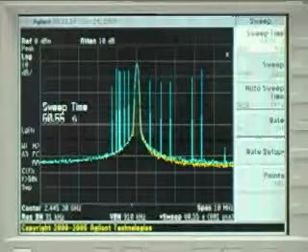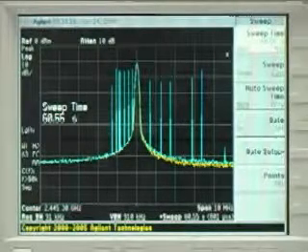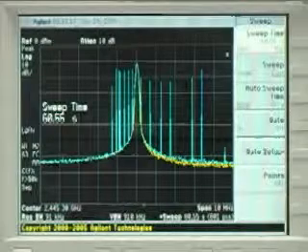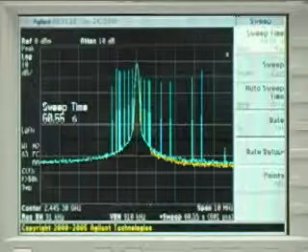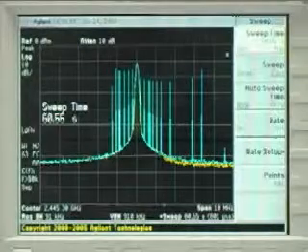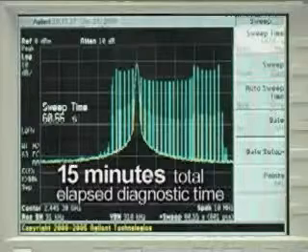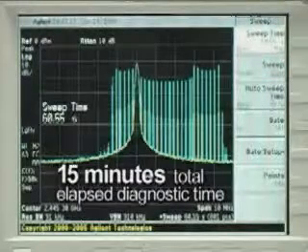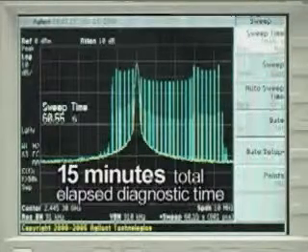With a sweep time that was slow enough, and particularly with a signal that happened to have occurred often enough that it could be captured, the Agilent PSA gave us a partial analysis. And how long did it take to get it? 15 minutes, with about 10 minutes using the fast sweep to figure out there was a problem, and another 5 minutes using the 1 minute sweep time trying to get some more information.